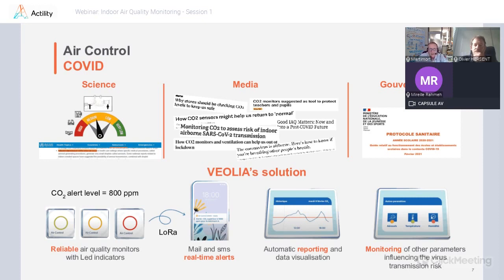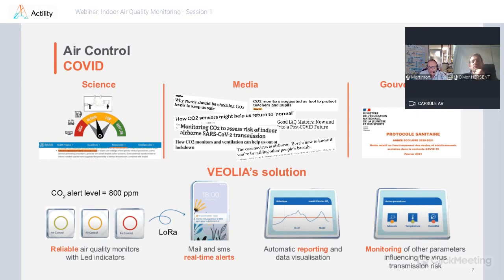Yeah. As you know, buildings have to have, for the health of the building, a minimum of ventilation, even when unoccupied. And this is the opportunity for the sensor to see the outdoor level of CO2, even if it's not effectively 400. In our case it's settable, of course, but it is based on the lowest value you can see over 2 weeks, 15 days. And then this is recorded, then applied. So this is an auto calibration, which is called ABC, automatic baseline calibration.